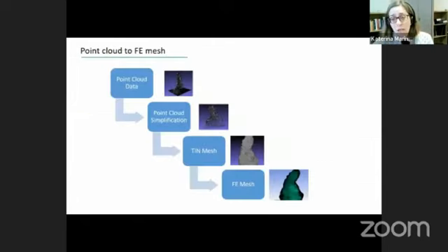Processes necessary to simplify and reconstruct the three-dimensional mesh model from point cloud data were performed, with operations comprising the point set simplification and the cleaning of data and surface reconstruction to create a thin watertight mesh. The open source tool MeshLab was used for the application of appropriate filters to approximate noisy data and produce smooth, robust surfaces with points that are uniformly distributed.